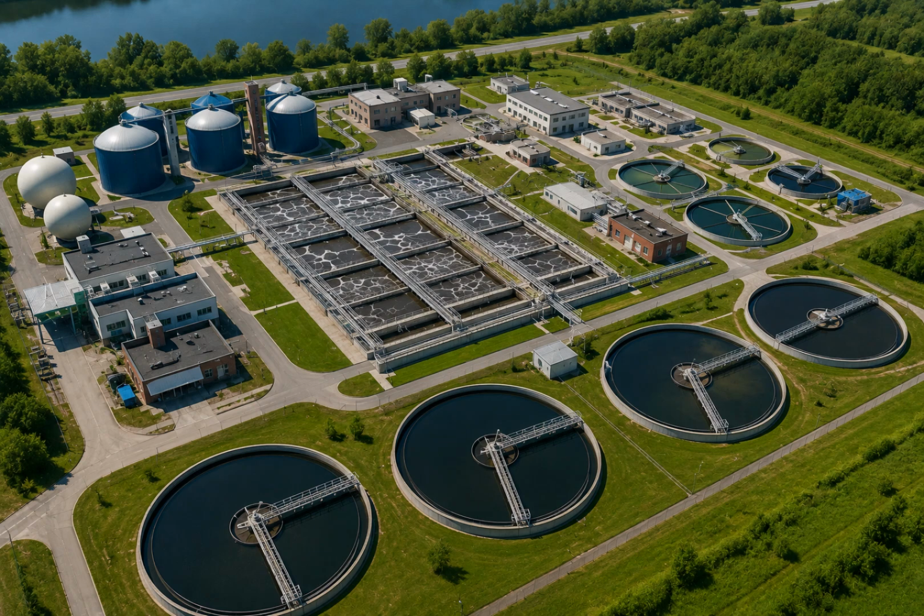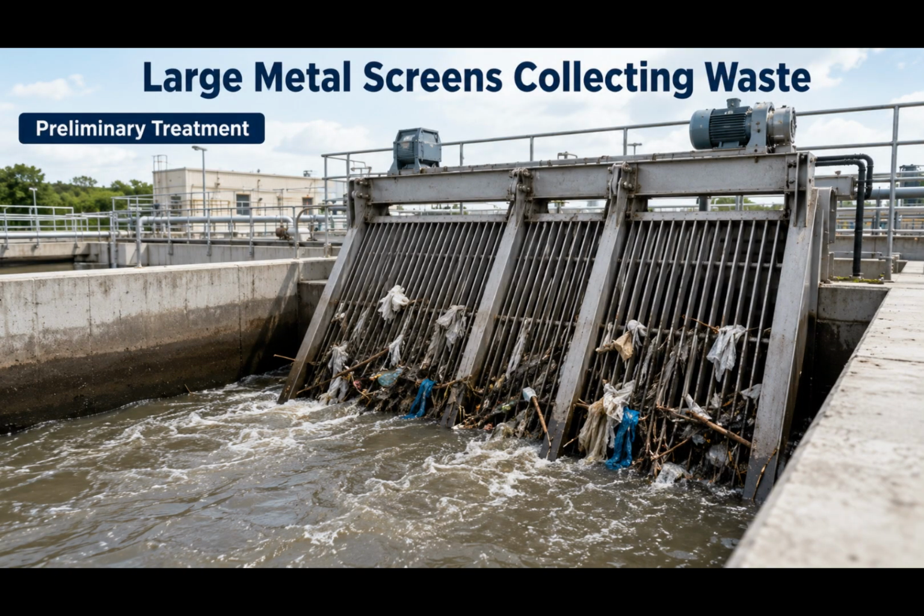The liquid then leaves the septic tank and enters a drain field, where it slowly passes through pipes, gravel, and soil. The soil provides additional filtration and helps remove some contaminants before the water reaches the groundwater. Unlike a septic system, which treats wastewater on the property where it is produced, a public sewer system transports wastewater to a centralised treatment plant.